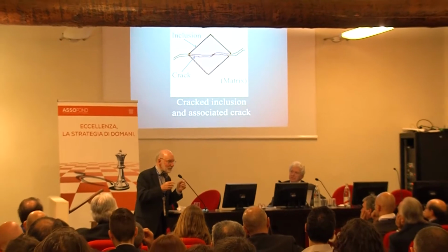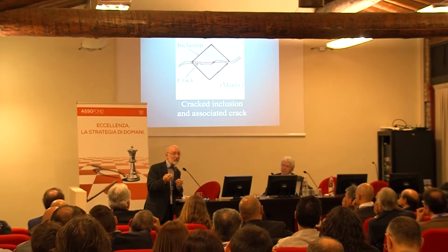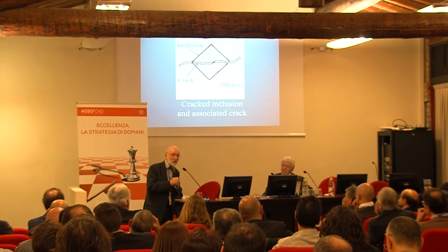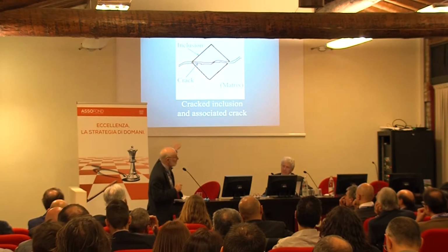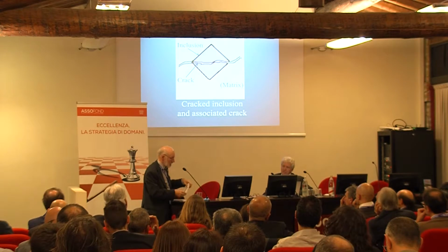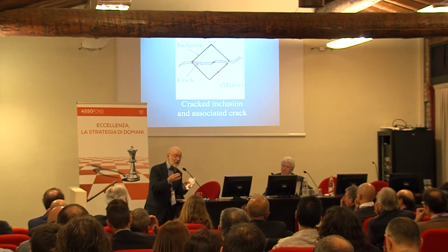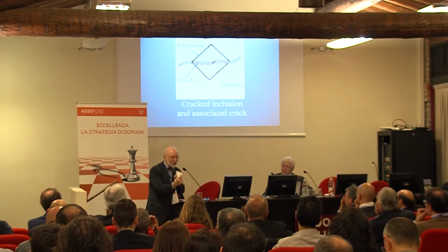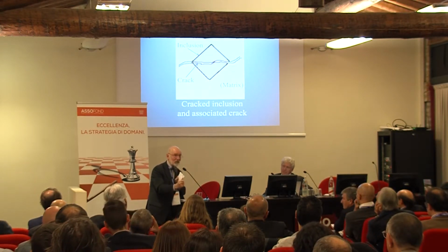So we have to rethink what we're doing with getting clean steels. The real thing is not to introduce cracks into our steels. That's the first thing that arrives here. The crack is there first, you remember? And then all the other phases, generally speaking, nucleate on the cracks themselves. They're not normal cracks. These are what I call oxide cracks or bifilms.